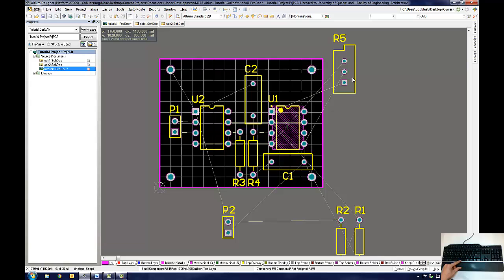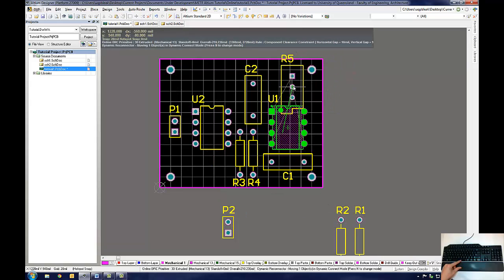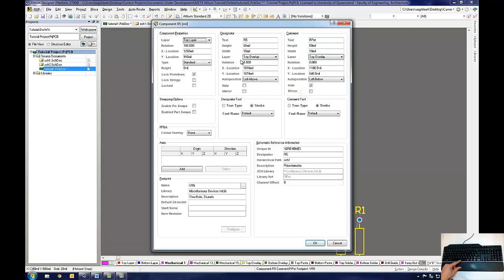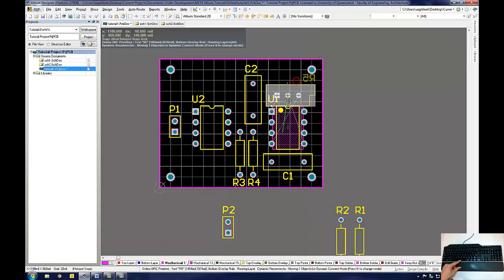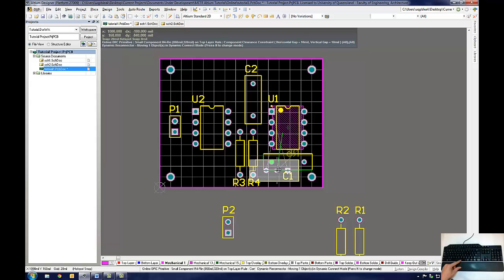It is often forgotten that components can be placed on both the top and bottom layers of the PCB. This technique can be used to save space. It can also be used to place tall components on one side of the board and low-profile components on the other. This can be effective if physical space is restricted within the enclosure of the product.